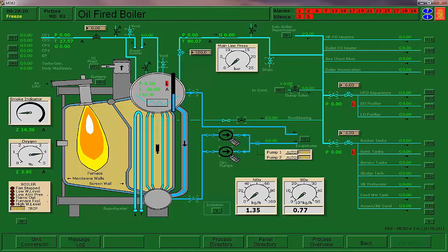Okay, and then on the boiler, this temperature, you have to be above 100 C. So you know, this was 30 minutes. This would start probably producing steam about 40-45 minutes. And in real life, as soon as I saw any steam coming out of the vent, if it hasn't been an hour, you shut the fire off. You wait until the hour time period is up, and then you light off again. And once that hour's up and you are producing steam, as soon as you have steam coming out the vent, the air cock, you can close it. As soon as I had steam and no water coming out of this drain, I would also close it. But again, with 30 minutes, that would be for the next watch.